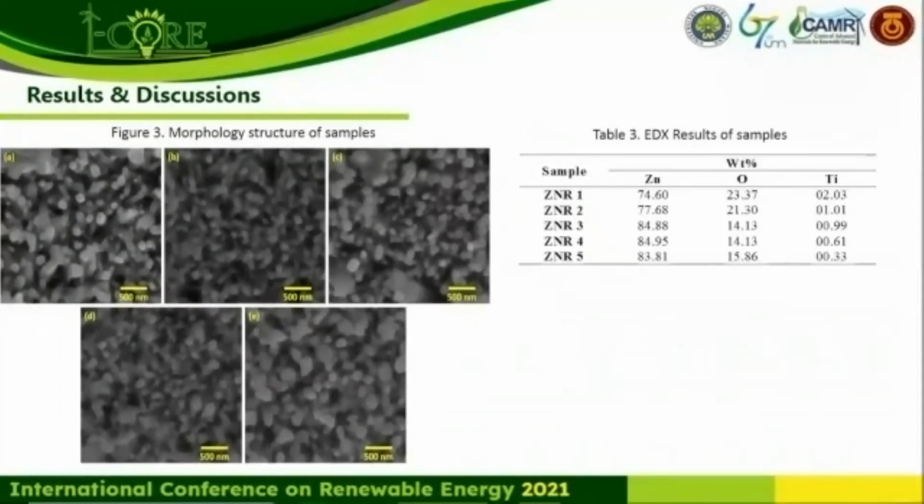And this is for the EDX results. The EDX results show that the sample contains elements of zinc, oxygen, and also titanium derived from the zinc oxide nanorods and TiO2 materials. It can be seen in table 3, the composition of weight percent from the zinc increases with the increasing hydrothermal durations in the sample for 1 hour until 4 hours, and then decreases